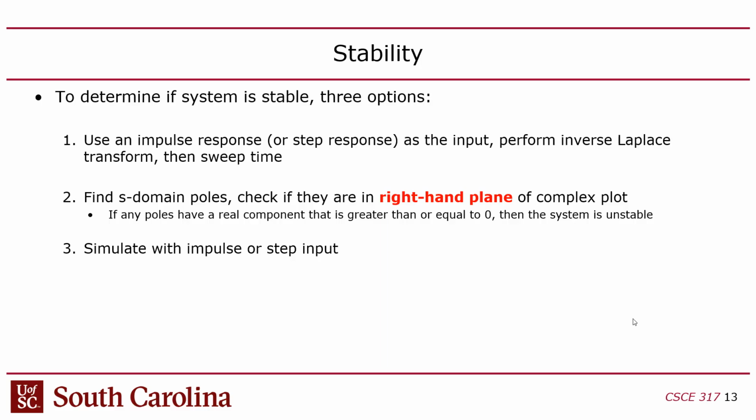That's also mathematical. Another way is more of an empirical approach, where you can take the system and simulate it in MATLAB or some kind of software tool with a step or an impulse response. So this is an empirical way to do it, right? You just test it, basically.